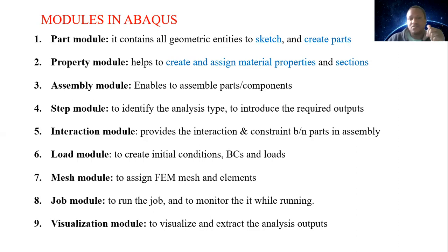Step module identifies the analysis step to introduce the required analysis output. And so, interaction module provides interaction and constraints between parts in assembly. And the load module helps to create initial conditions, boundary conditions, and the load. And the mesh module to assign the finite element mesh and the elements. And job to run the job and to monitor it while running. And finally, the visualization module helps to visualize and extract the analysis output.